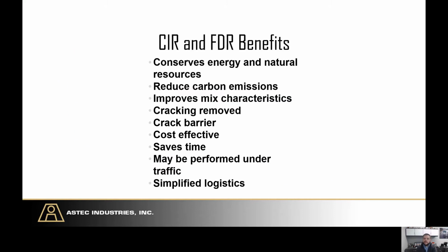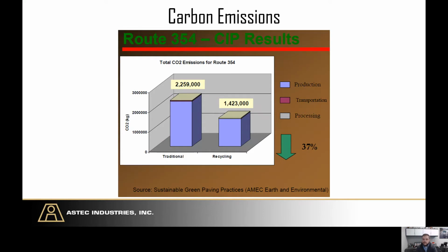Of course, there's all the other sort of benefits. We're conserving energy and natural resources, reducing carbon emissions, and then some of the other things we've talked about. When you're looking at carbon emissions, this is a study from AMEC, Earth and Environmental up in Canada, looking at CO2 emissions for traditional practices, so more of those mill and fills, those sort of things, overlays, versus recycle. Because you don't have that trucking, it ends up in a 37% reduction in CO2 emissions.